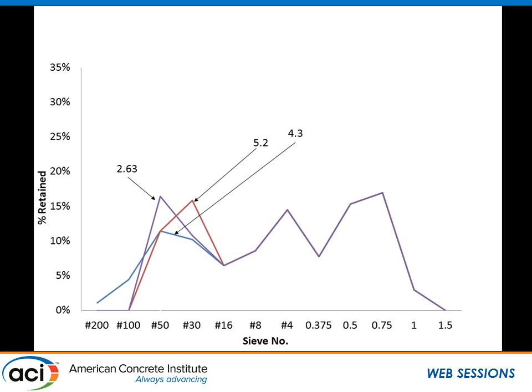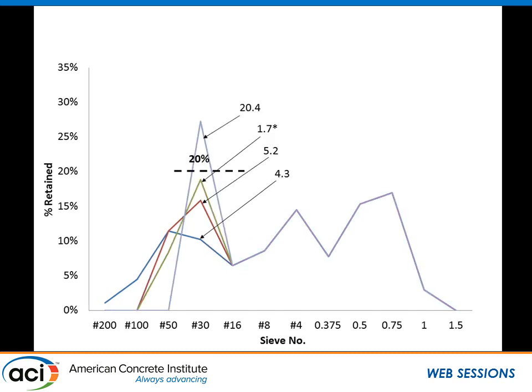And we can see as we teeter-totter around here, as we move to different places, we don't see drastic increases in water reducer dosage. So we don't see big impacts on the workability from these fine sands. Okay, we can do all kinds of stuff like this, where we can ramp these things up and down.